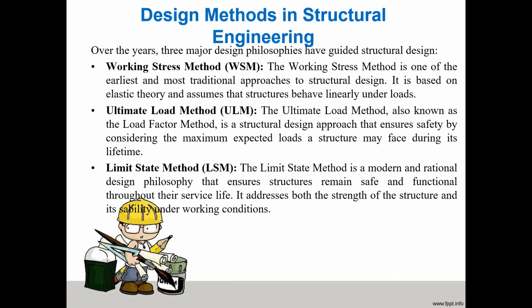About design methods in structural engineering: over the years, three major design philosophies have guided structural design. That is, first one is working stress method, second is ultimate load method, third is limit state method. Working stress method is one of the earliest and most traditional approaches to structural design. It is based on elastic theory and assumes that the structure behaves linearly under loads.